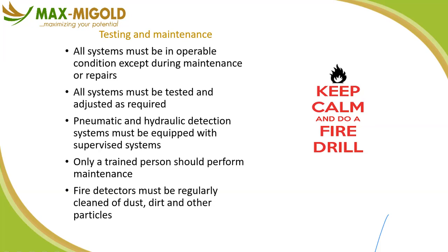And for the maintenance, also note that fire detectors should be considered. So the cleaning or service and fire security of fire detectors should also be considered. So you need to clean the dust, or let's say blow the dust, all right, and ensure that there is continuity from the fire panel for every single zone of the smoke detectors. Next slide, please.